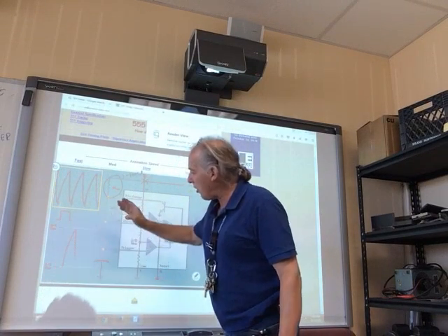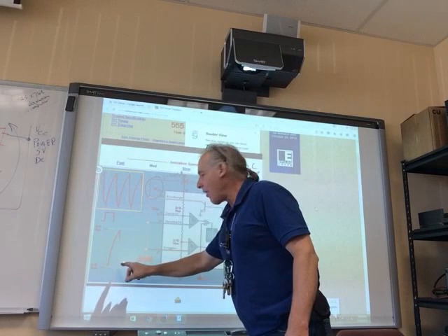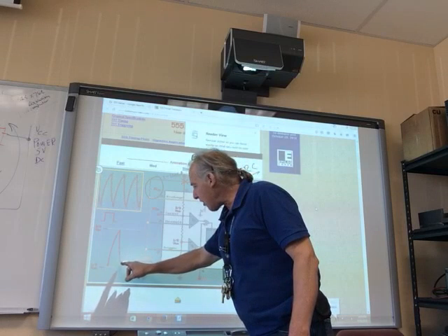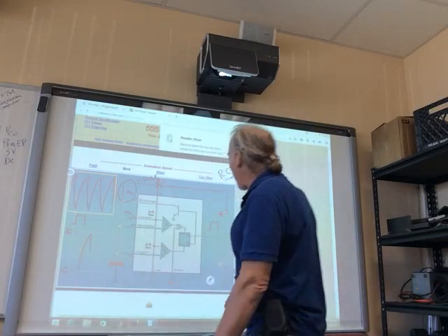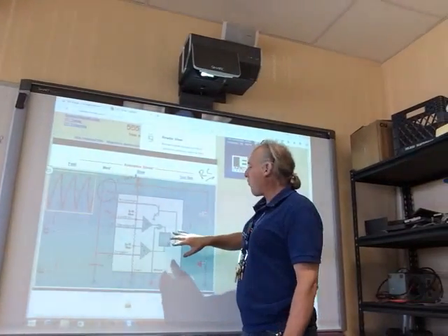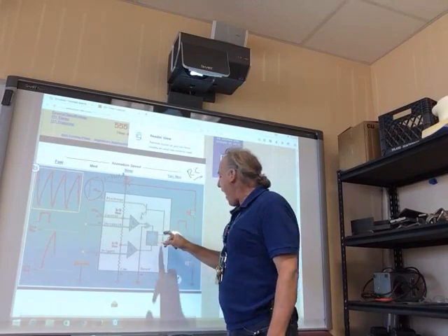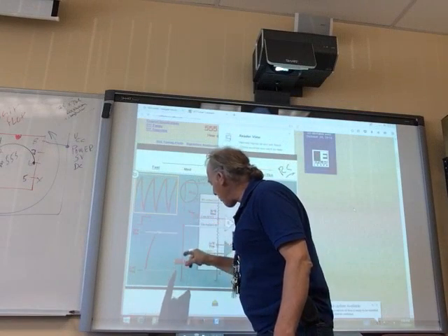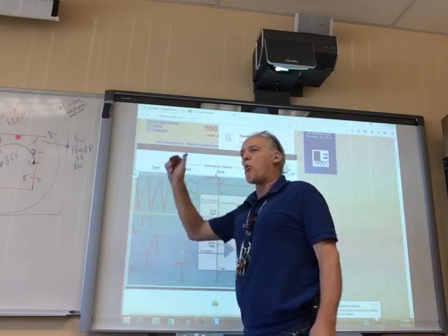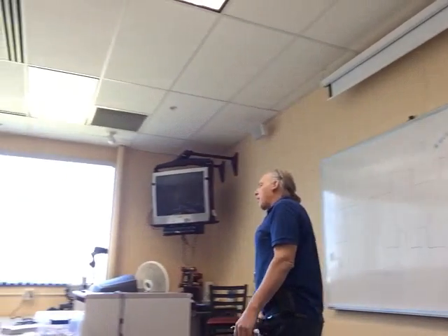It shorts out. Notice it's pretty straight, but notice it doesn't get all the way down. And watch what it's going to do here. See, it's starting to curve right there. You see it just started to curve. When it hits that point, what happens is the flip-flop flips back over, turns the relay off, output changes, and guess what? This resistor charges up this capacitor resistor network, and boom, we're on our way again. And that's all it does. Just sits and does that all day long, depending on what components you put in there. Make sense?